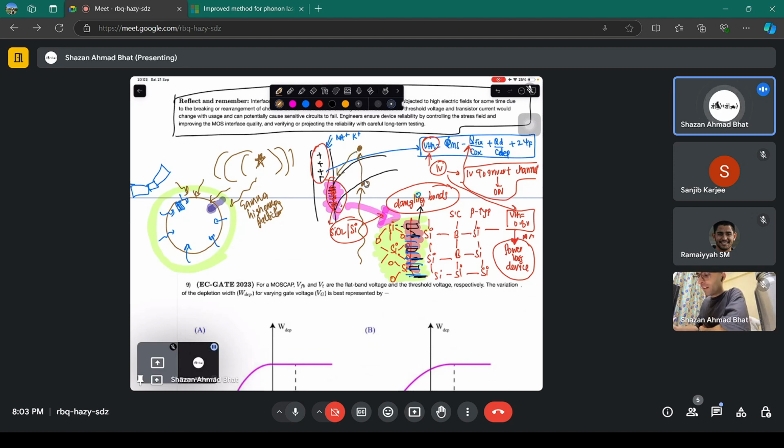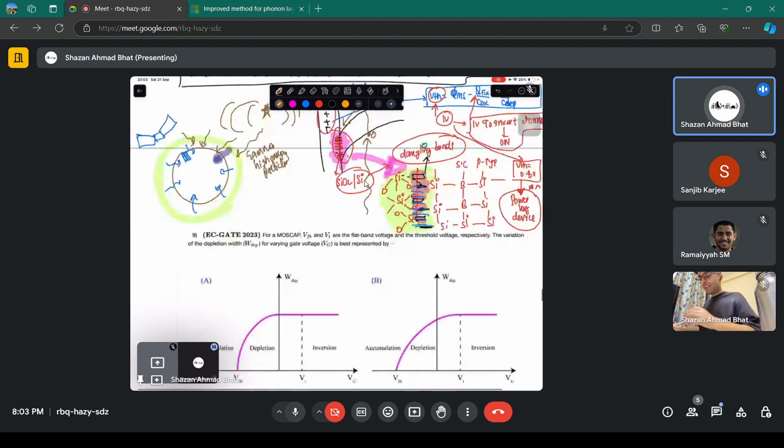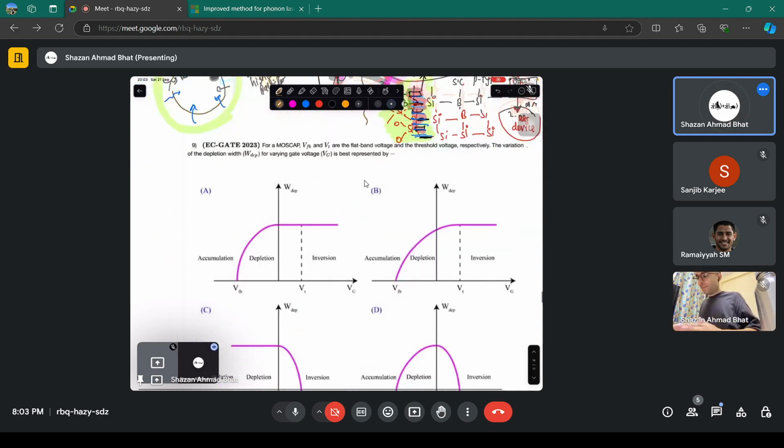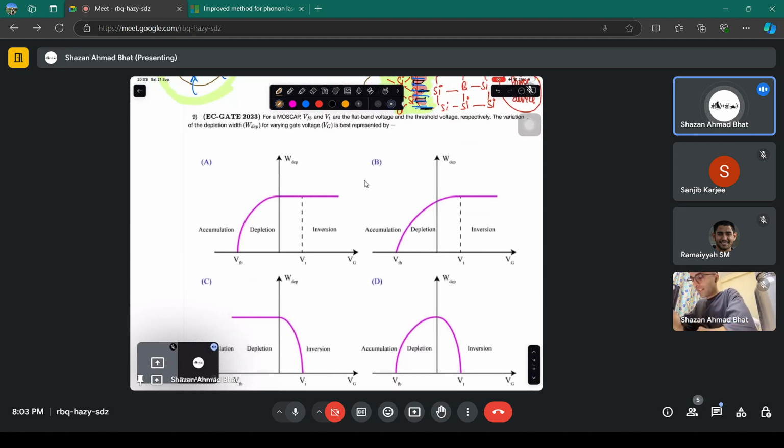The electron can go in and change the threshold voltage, and the device may behave weirdly. Sometimes whenever there's a star burst somewhere in the universe, people on Earth get glitches in their devices, and most scientists believe it's because of this. It's a much deeper story. Let's not go into that depth, but we can discuss it someday.